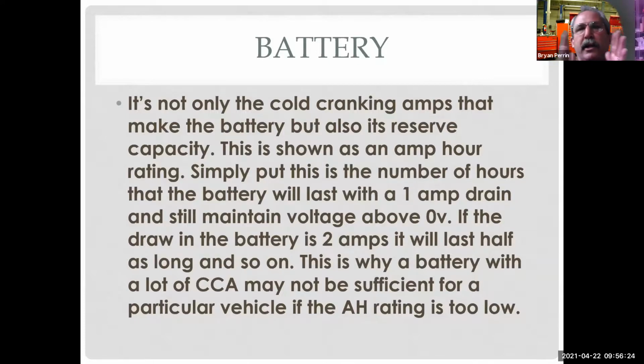So again, we have a benchmark test. My battery is dead a long time before it gets to 0 volts. I can't do anything with it. But this is a benchmark test that allows me to compare battery A to battery B to battery C. Some manufacturers require a lot of reserve capacity, 125 amp hours. Other manufacturers might only require 60 or 80 amp hours.